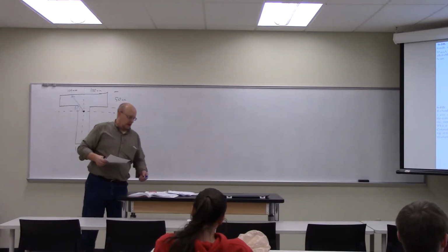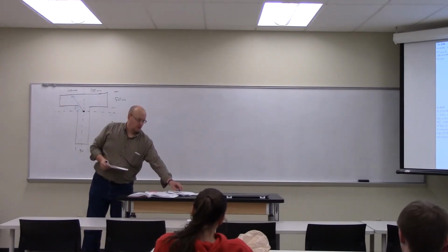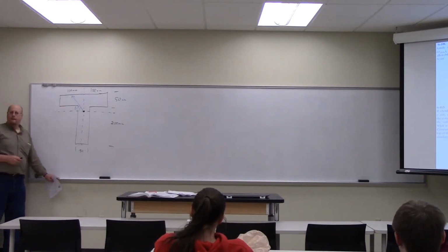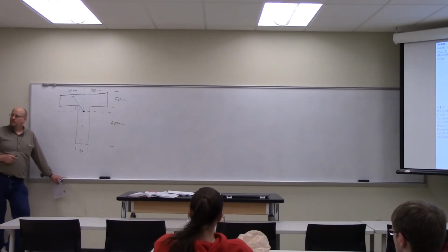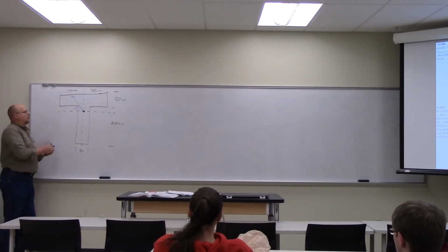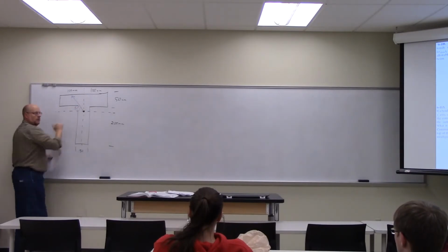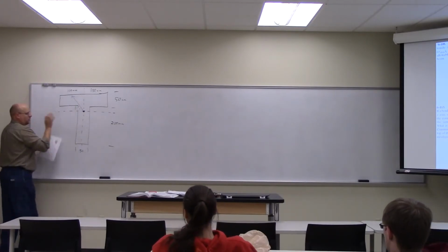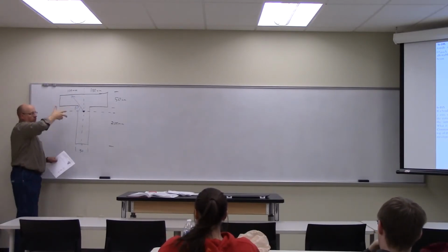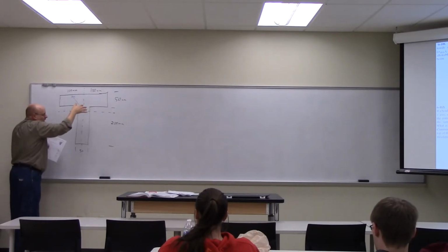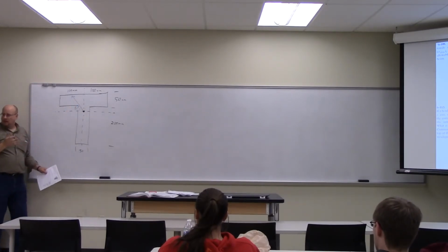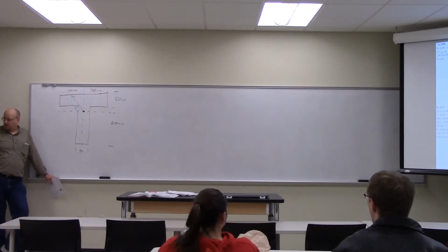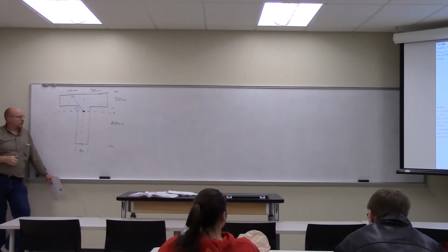So, is the applied moment along a principal axis? Yes or no? Can I ask a quick question to visualize the moment? How would you apply a moment? I would take it and twist it like this. Your thumb points along the moment. I'm taking this beam and trying to bend it. I'm not twisting it, sorry, I shouldn't say twist. I'm bending it in this direction. I'm always bending it perpendicular to the moment, because with the right-hand rule the thumb is always perpendicular.